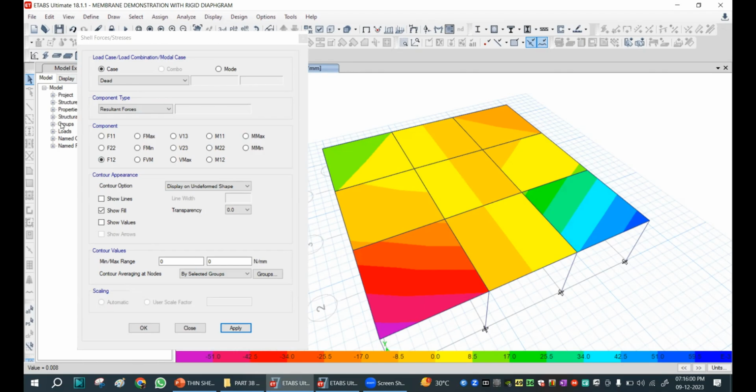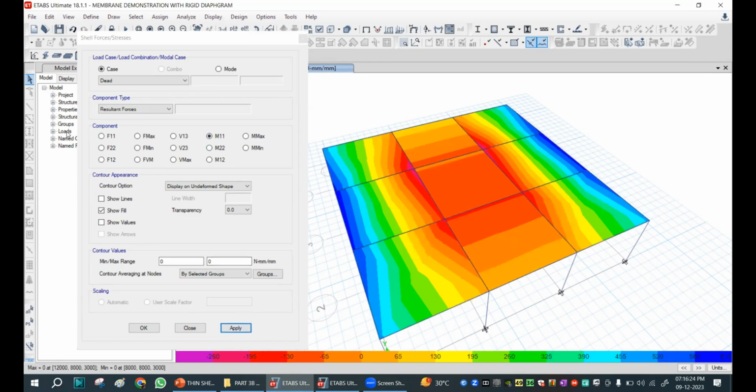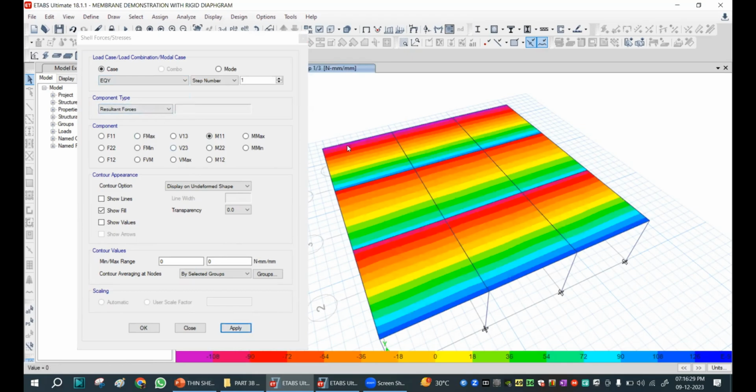So in ETABS, we have a feature that in-plane loads can be eliminated with diaphragms. That we will see when we are going to understand this, that in-plane and out-of-plane loads can be eliminated by diaphragm. That we will see when we are going into the concept of diaphragms. Okay. So for now, we can neglect this in-plane stiffnesses. Only out of plane we have to check because we will check for the vertical as well as lateral load. So for the lateral load, in-plane loads have been neglected.